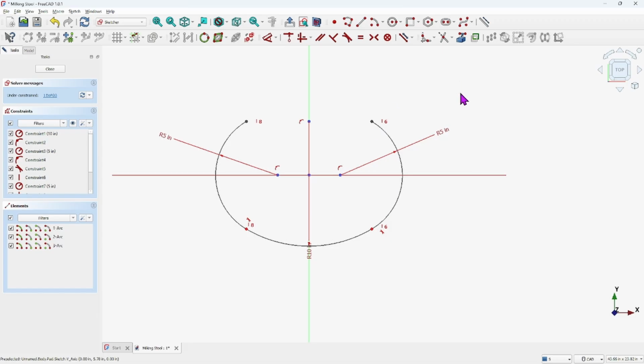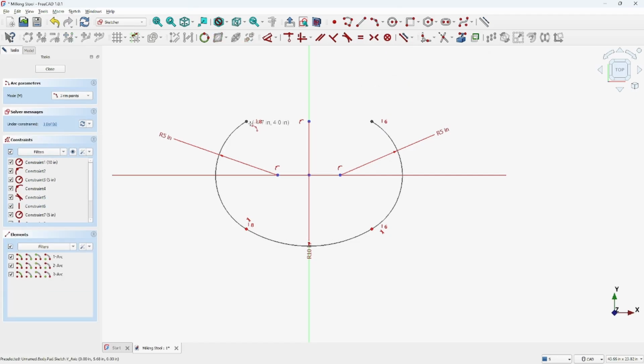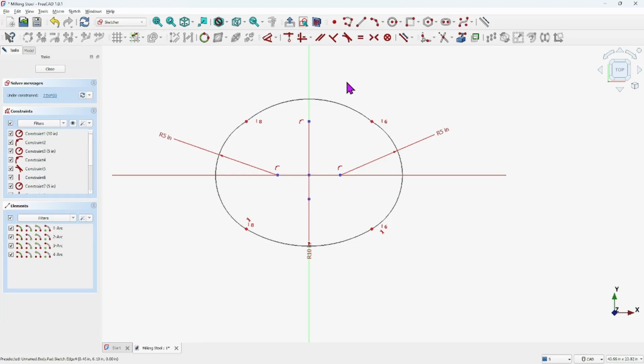So then this piece is all we need. You know, we could mirror this, but I think I know what I want to do. I think I'm just going to do a 3-point. So I can grab the two endpoints. There you go, that's locked in. Now I just need something like that. If I just select it there, right click to get out and give that a radius of 10. I've got it selected. Give it a radius of 10. It should be exactly what we're looking for.